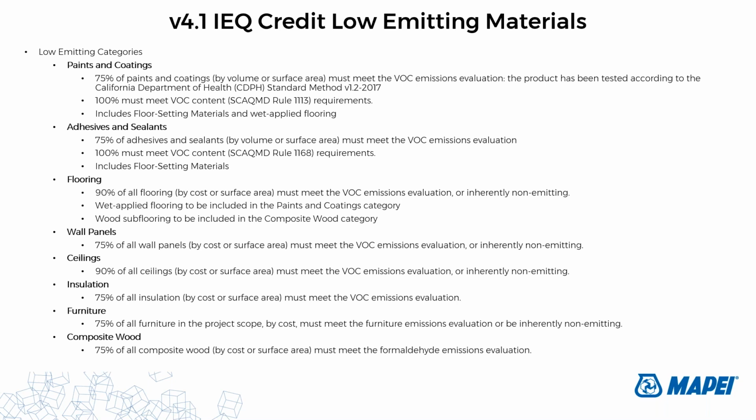You have to meet the composite wood category requirements, which states that 75% of composite wood, including wood subflooring, meets the formaldehyde emissions evaluation, showing that a product is certified as ultra low emitting formaldehyde, or ULEF, and or certified as having no added formaldehyde.